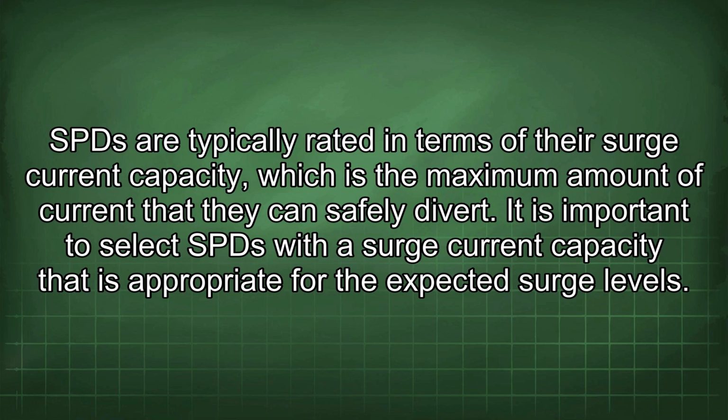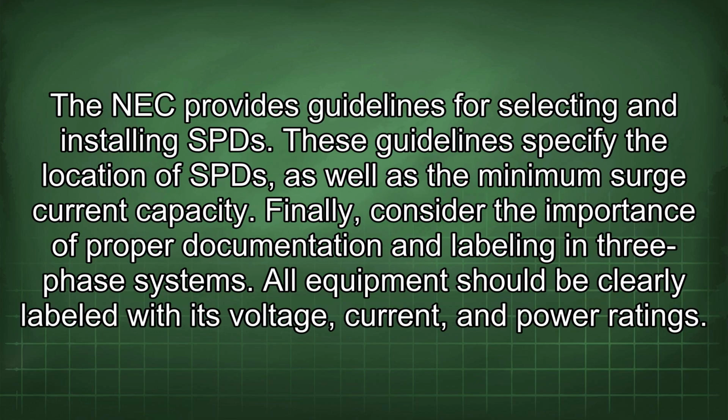It is important to select SPDs with a surge current capacity that is appropriate for the expected surge levels. The NEC provides guidelines for selecting and installing SPDs. These guidelines specify the location of SPDs, as well as the minimum surge current capacity.